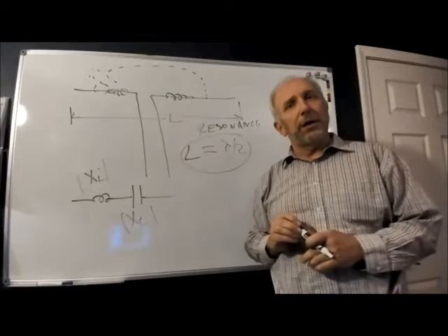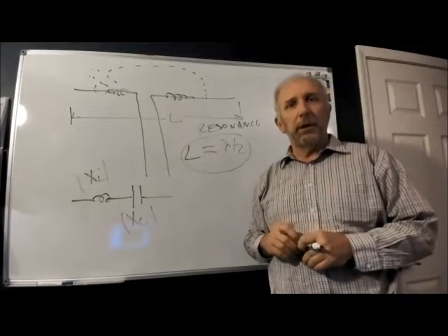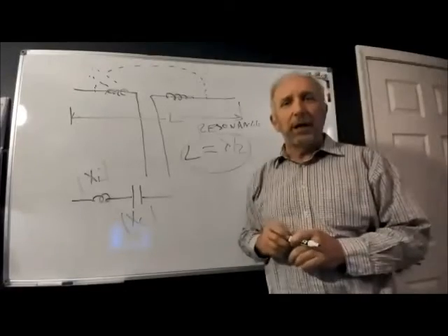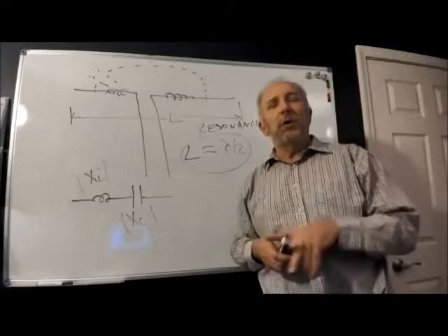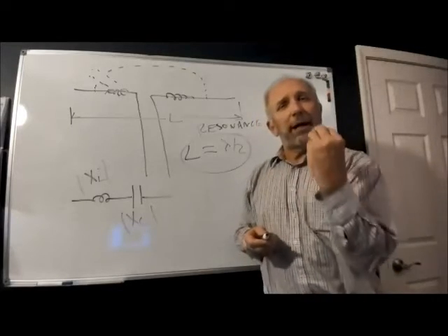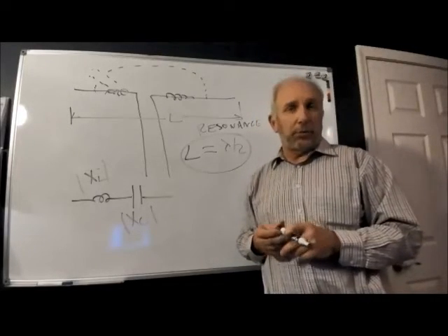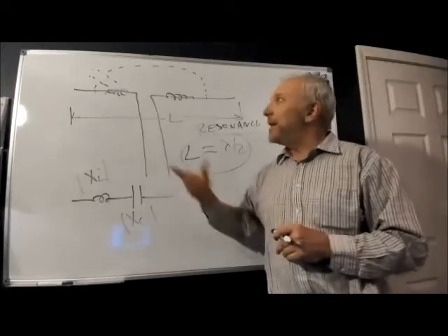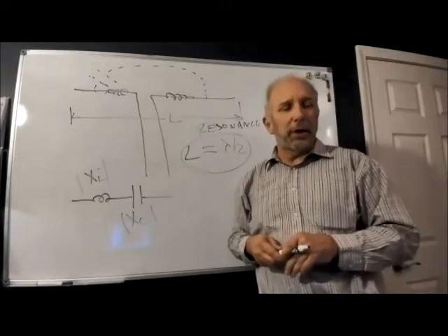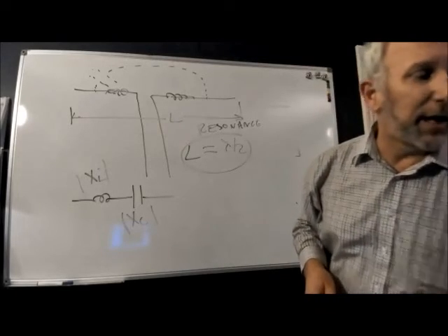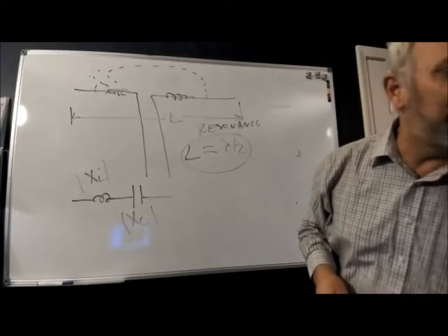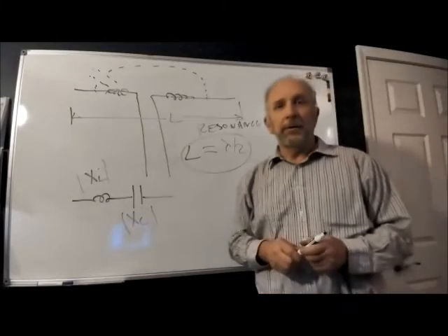Is that a good thing or is that a bad thing? Depends. Absolutely. If you want to use an antenna for some specific purpose, you probably want a resonant antenna. If you for some reason create a resonant antenna structure in your product, your system, your device, it may be a really, really good antenna and cause you now to fail. Radiated emissions and all other kinds of bad things could happen. Questions on that?